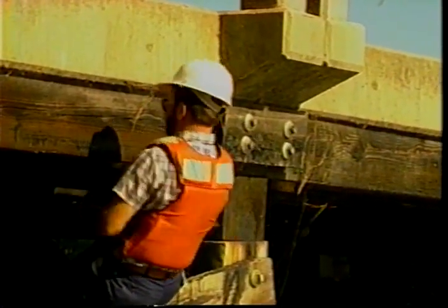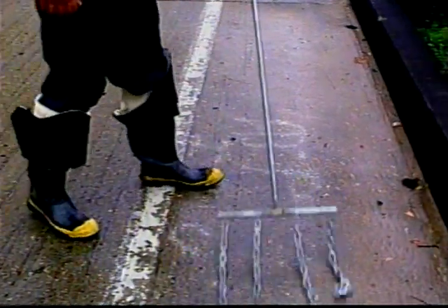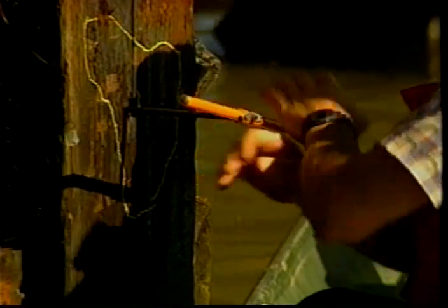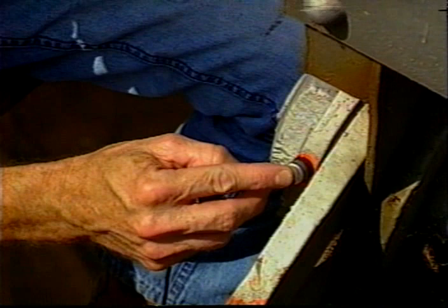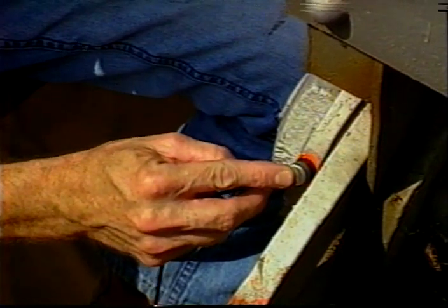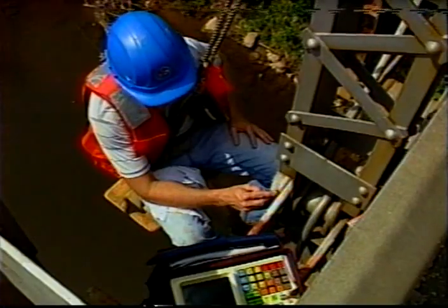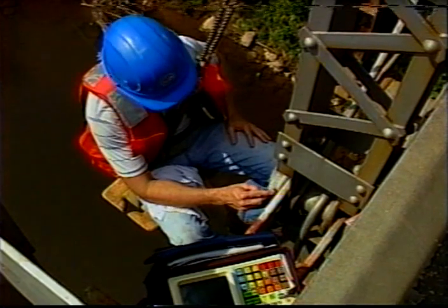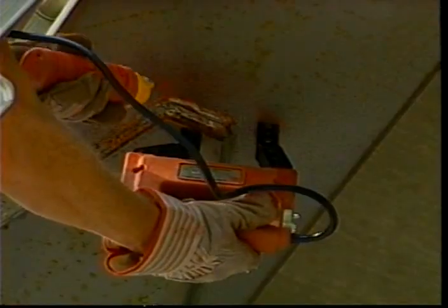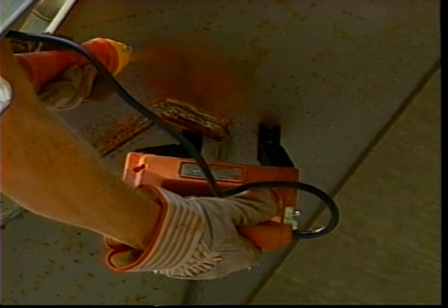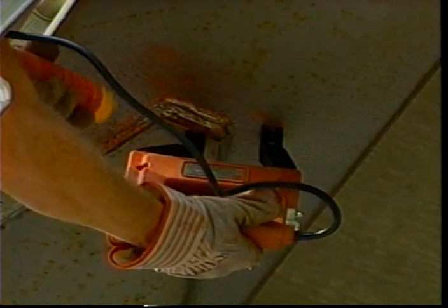Sonic methods are used to detect hollow areas and delaminations in timber and concrete members. Hollow areas found in timber members can be further examined by coring into the wood to remove a sample for study to measure the void size. Ultrasonic techniques are used to detect cracks, delaminations, and other deficiencies in welds, steel members, and timber members. Cracks in steel members can also be detected by inducing a magnetic field with a power source.